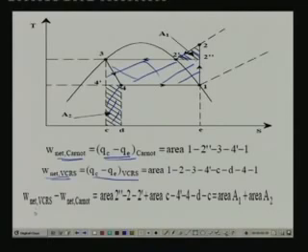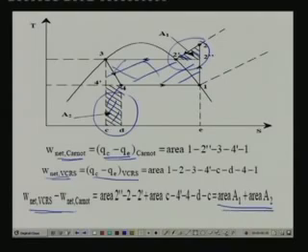Okay, so you find that the difference between the net work input of a standard cycle minus Carnot cycle is nothing but this area, that means the rectangular area 1 2 dash 3 4 dash plus superheat horn area A1 plus throttling area A2. Okay, that means the difference is nothing but area A1 plus area A2. Okay, this area and this area, right.